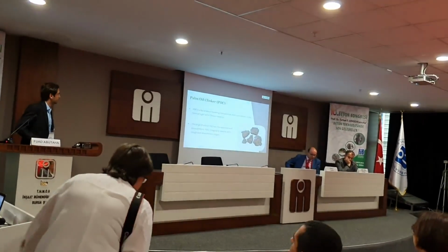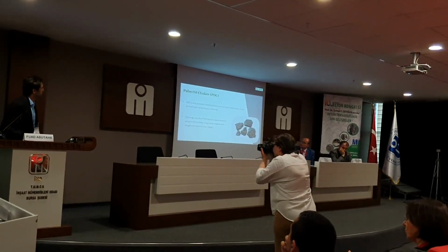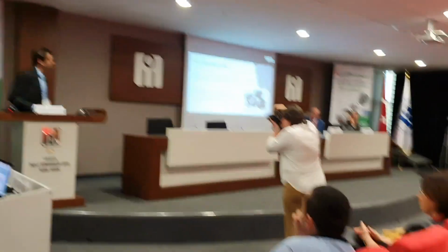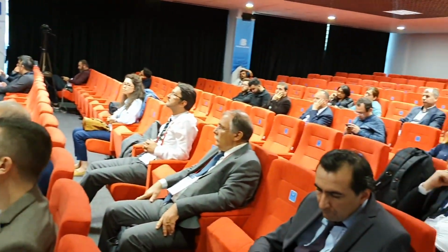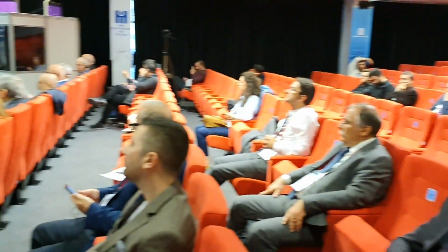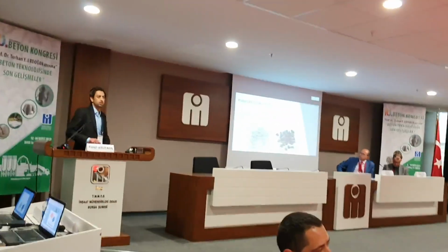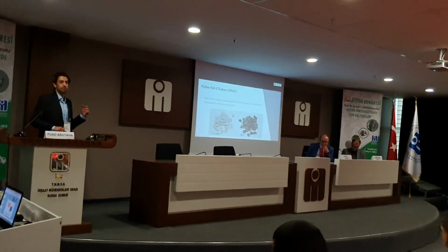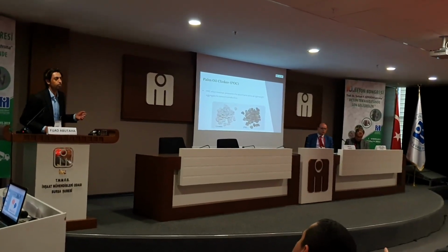The palm oil clinker is a byproduct resulting from the palm oil shell incineration, in the form of a solid fibrous material. It's a green color, as you can see. The appearance is porous, fibrous, flaky, irregular in shape with sharp and rough broken edges, as you can see from the picture. So initially, from my point of view, when I started this research, this waste material, POC, when crushed, possessed the potential to be used as aggregate in concrete production.